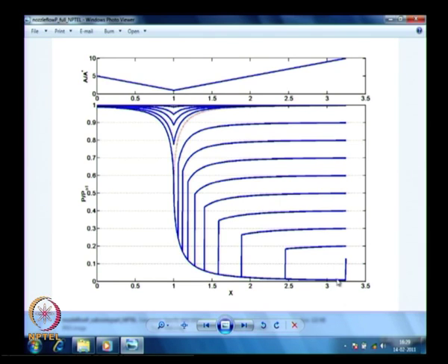Okay. If I think about this particular case, it is probably 0.1 going to around 1.8, which is like 18 times increase in pressure, while at this particular condition it is roughly 0.1 going to 0.5, that is 5 times increase. Okay. Pressure has been increased by 5 times roughly here, around 18 times here. So, it is increasing much more, while the very first curve we had, it was around 2.4 times or so. So, it is increasing drastically, okay. That is what is really the truth.